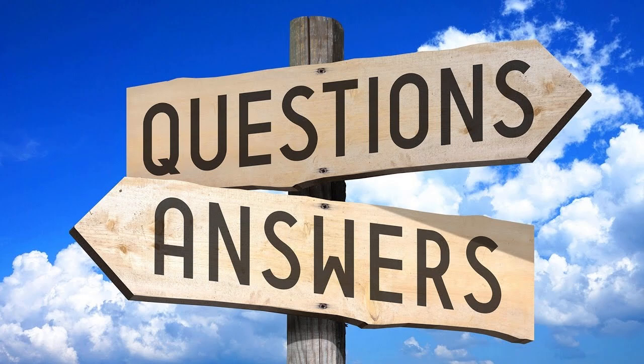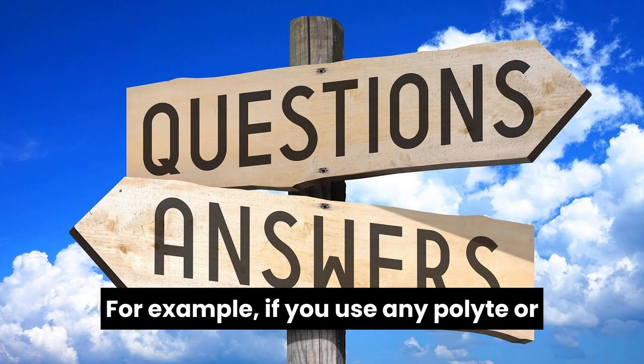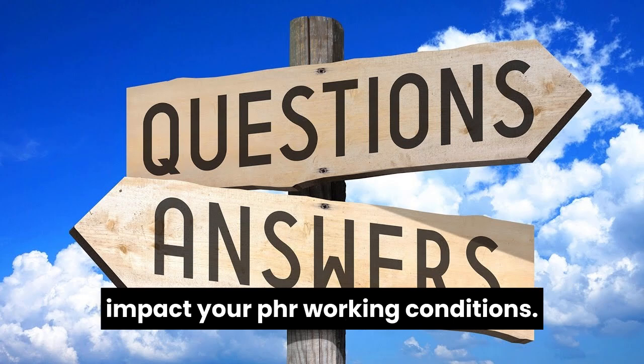Sir, when we use these chemicals, will there be any effect on the biological process or not? Sir, those chemicals are very small volume chemicals. For example, if you use any polyelectrolyte or ferric alum, the dosage will be 2 to 3 ppm, and more than that will not have any effect. They don't impact your pH or working conditions.